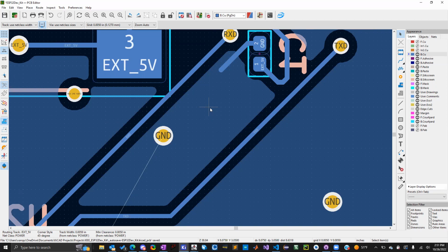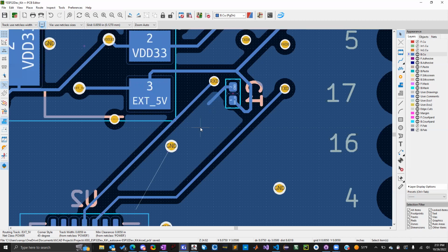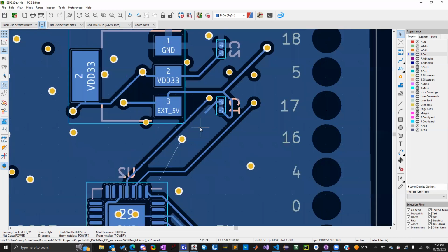It's just not good, not recommended. It's a very niche, very uncommon thing that you would have to do to create an analog and a digital ground. The most common things you're going to do is create a ground plane and a power plane or even a power pour, because you really don't want your tracks burning up and going into flames.